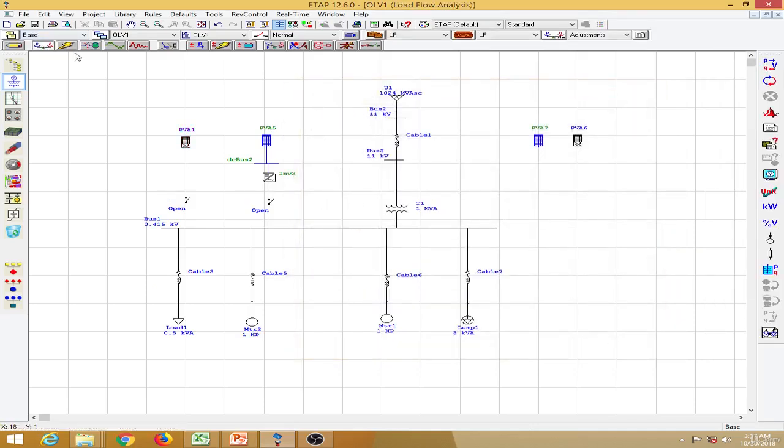So let me conduct a load flow without our grid-tied inverter systems over here. You get the 6 kilowatts of power flowing from the utility to our system. So 6 kilowatts into the duration of 6 hours gives us the energy requirement.